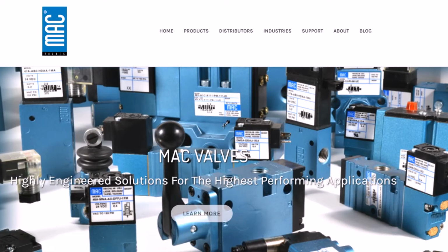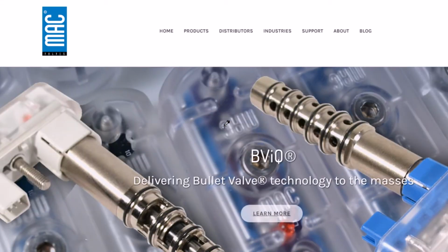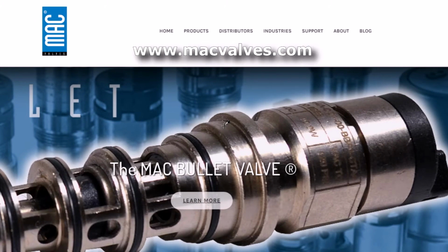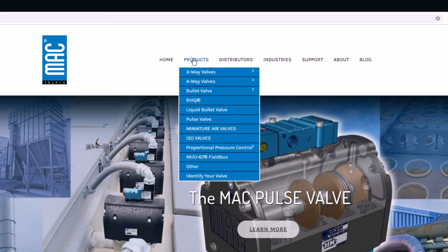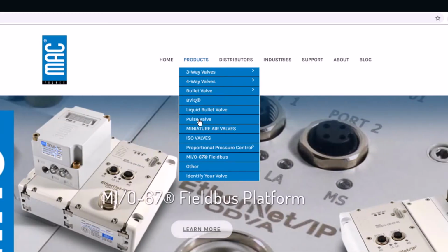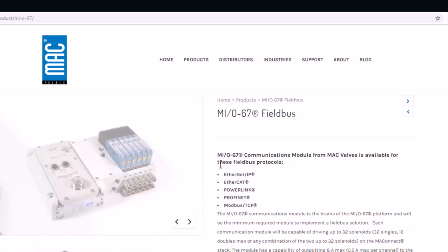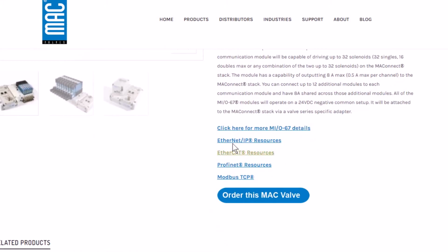In order to obtain the resources we need to configure our valve stack, we need to visit macvalves.com's website and visit the products link. Then go to the MIO-67 Field Bus menu. Here we will find different resources for other types of field bus protocols that are available. This video series is going to focus on Ethernet IP.